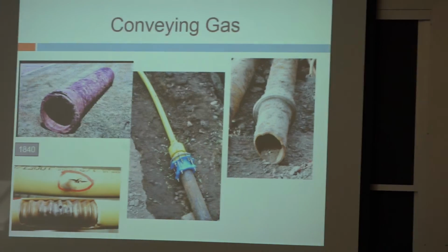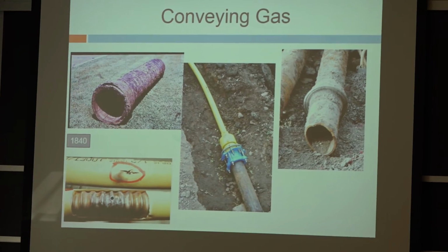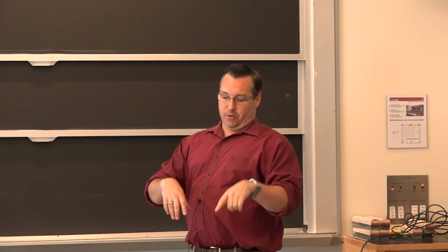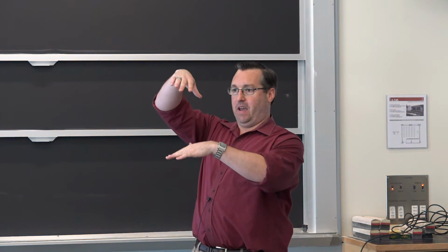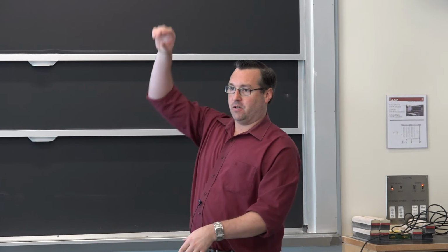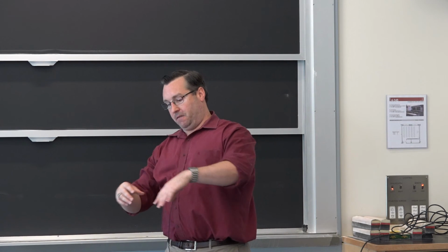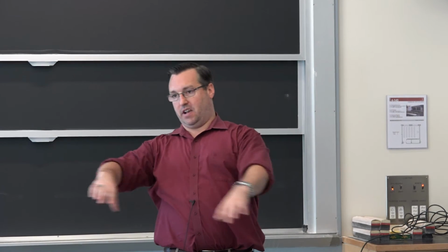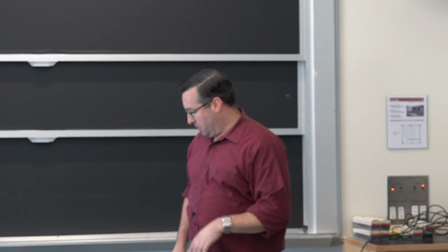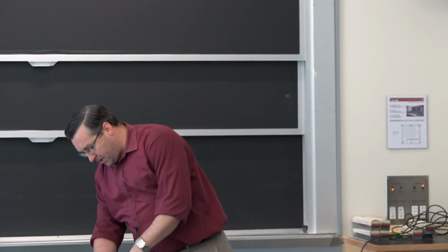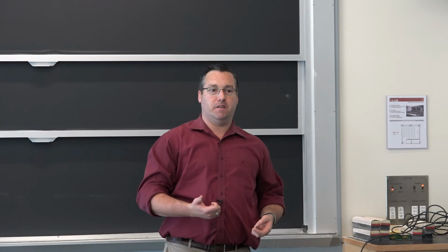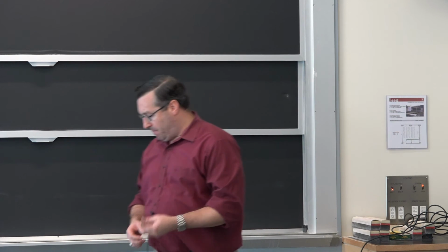it's a movie video. Anyways, there are YouTube videos out there that show these wire rope tests they do at the manufacturers. This one was the one I performed. The setup was vertical, so it was 3 stories. At a lot of the manufacturing facilities, you have size constraints, so they set it up horizontally and do those tests. Another type of test that you have to do, we talked about fracture toughness, is a Charpy impact test.